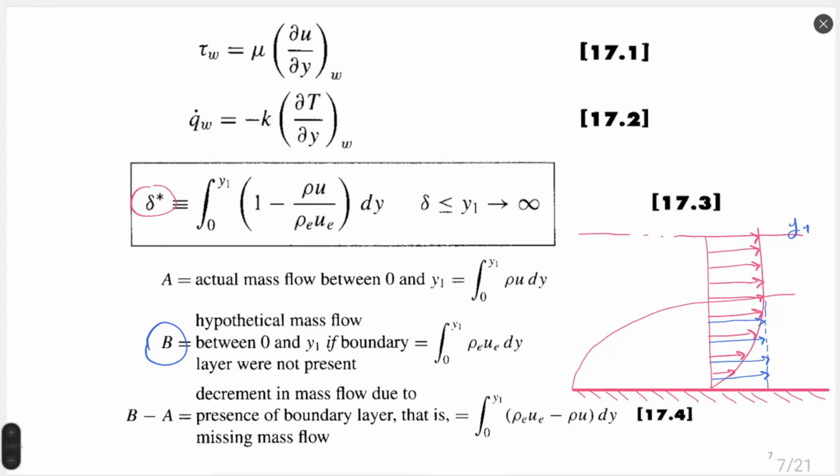How we do it? We multiply density by velocity and integrate. Once this velocity is constant, we can substitute by just a product. I will write here that this is density multiplied by velocity and multiplied by y1 coordinate. This is bidimensional case. It's not three-dimensional. So my area is equal y1.